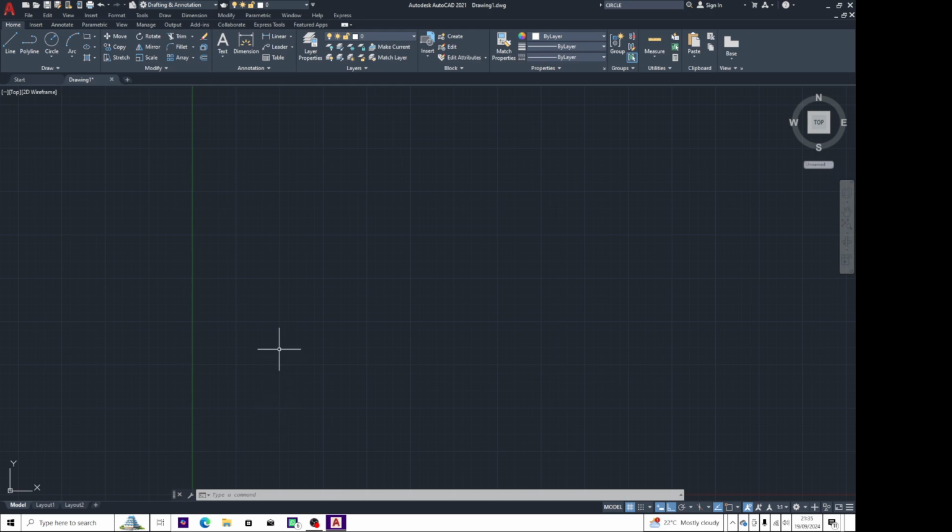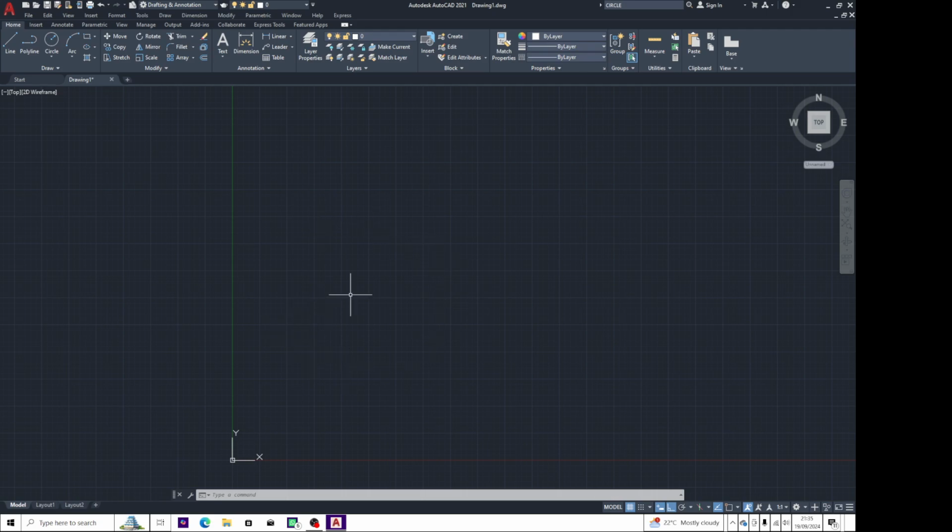And in this drawing space or drawing window, you can remove these grids by pressing just F7, function key 7 on your keyboard, and they can go away or come back. They can go simultaneously like that. That is our model space.